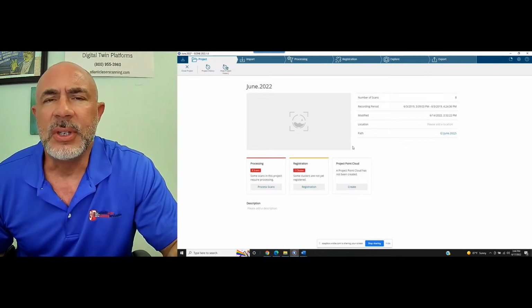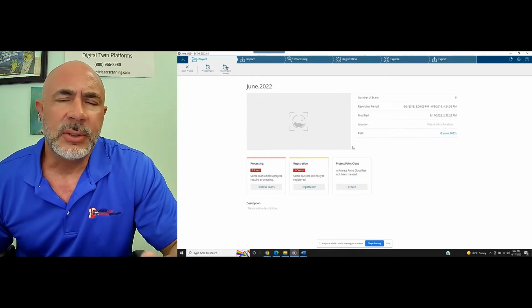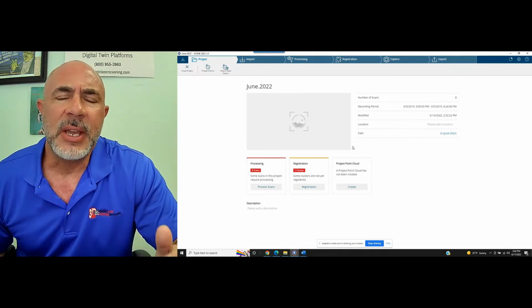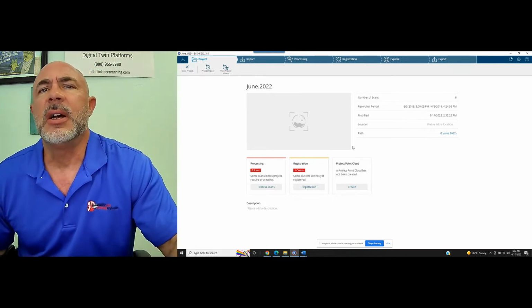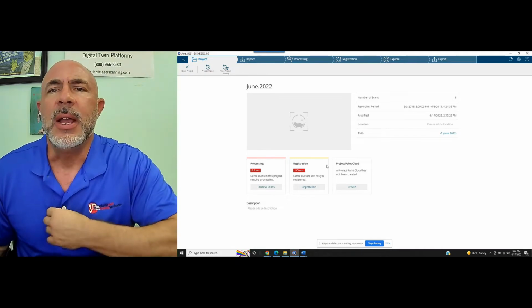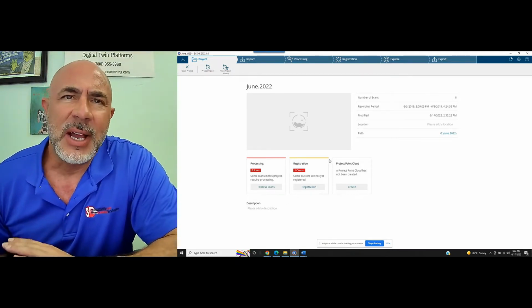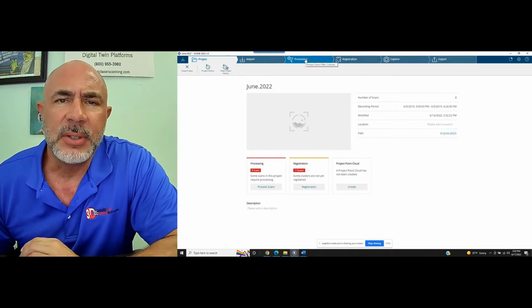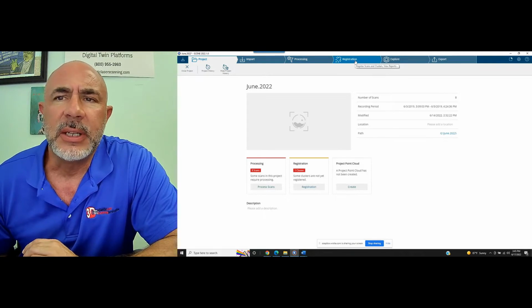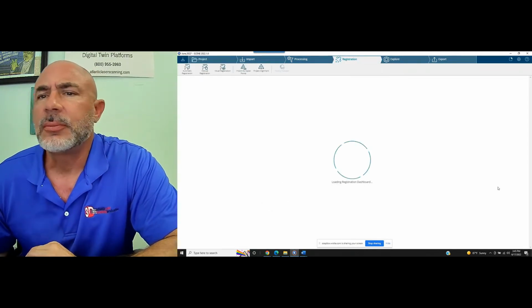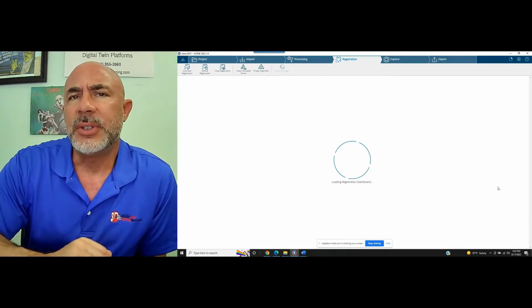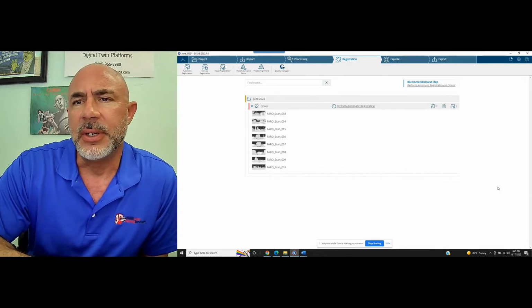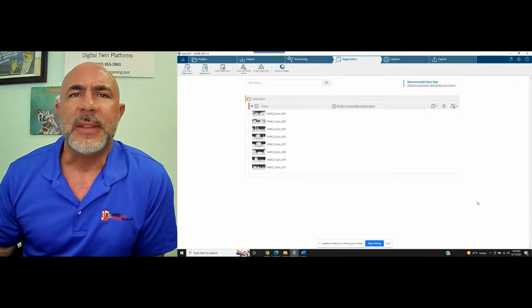and this is the screen that's going to come up. So whatever name you gave the project in the scanner, obviously you can see is the project's name when you pull it up. So this is, again, a building facade scan. There are no targets used, so we are not going to go into pre-processing, and we are going to go directly into registration. Now, you've got a default registration method that FARO uses when there are no targets used. So we're going to look at that real quick.